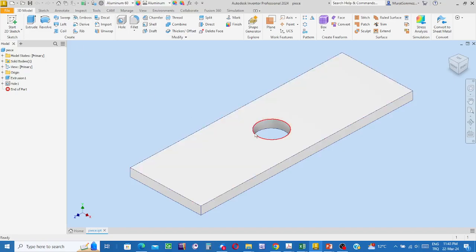But in doing this, I know from the theory and also experimental remarks, from theory of elasticity, theory of plasticity, and some case studies, in the vicinity of the discontinuity, here it is a hole, where the stress will be maximum, and the vicinity of the discontinuity is the place where there will be stress concentrations.